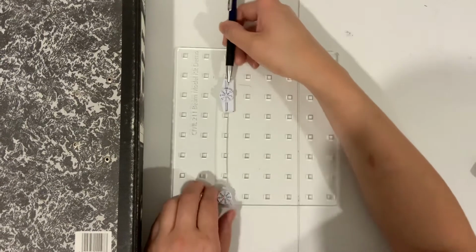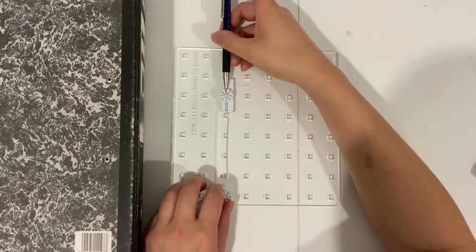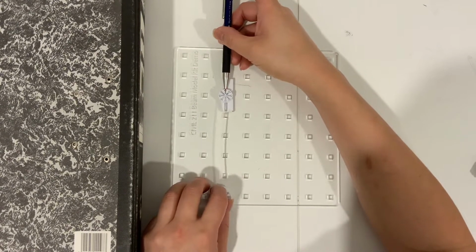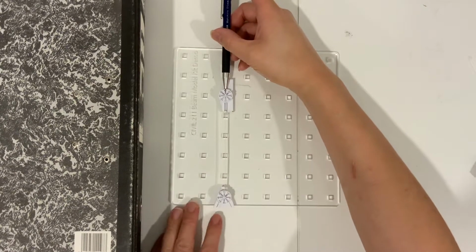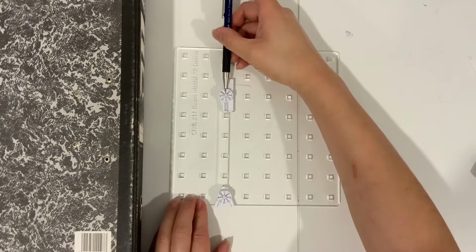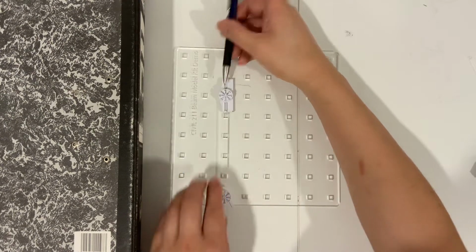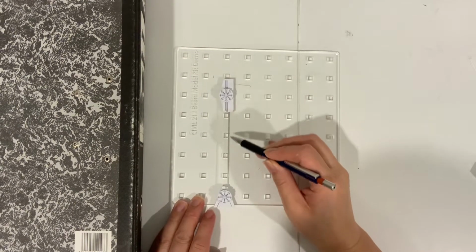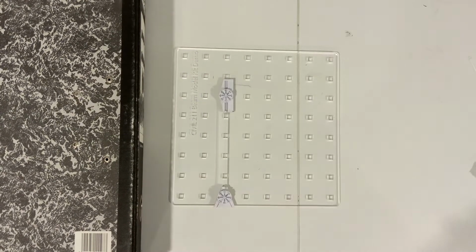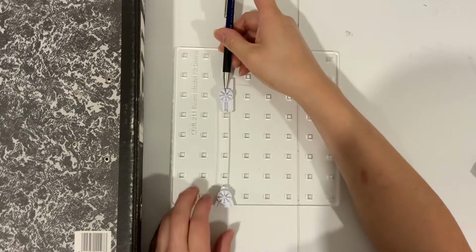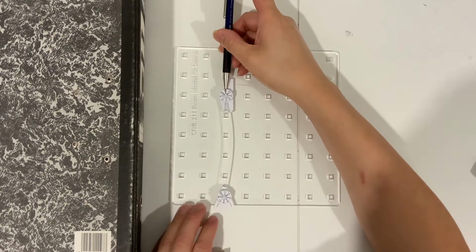But when I stick a load down in the opposite direction, it becomes unstable. So here I'm putting a small load on, and you can see even with a small load on, it wants to buckle outwards. Okay, so even with a small load, it would want to buckle outwards.